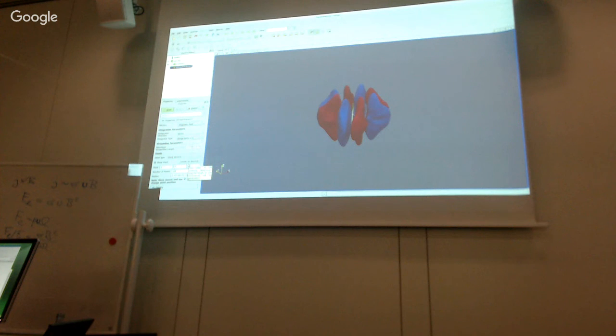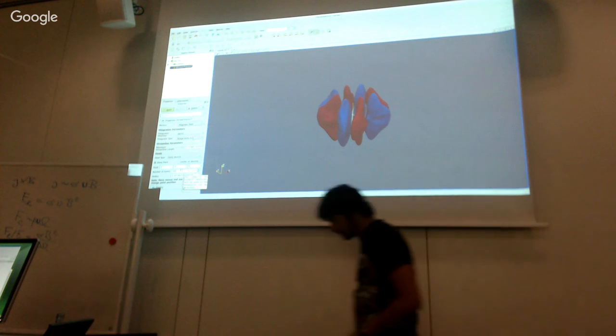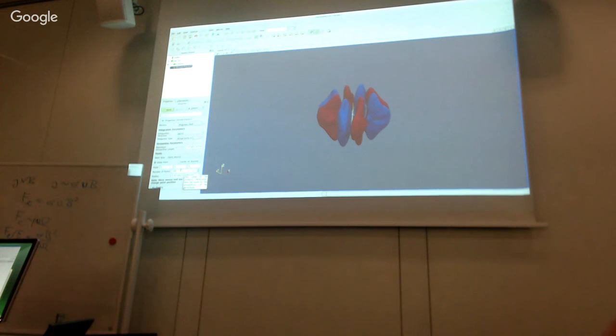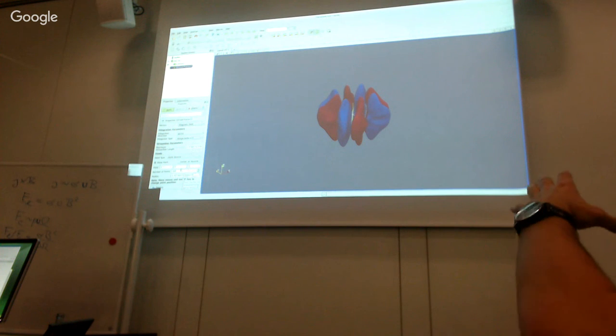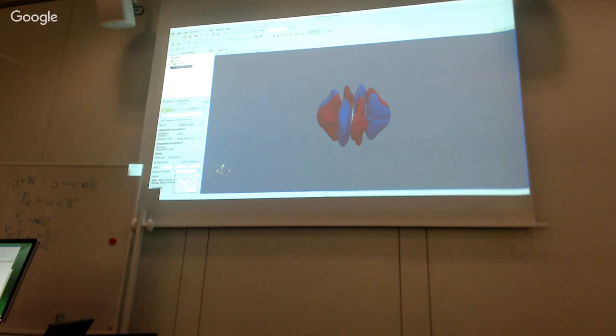You don't touch the advanced options. What ParaView does is that it spreads some random seed points throughout your domain. And for each of these seed points, it tries to calculate the field line which passes through the seed point. By default, it's just putting some random seed points throughout the spherical domain. And this is the radius it picks up by default, so 0.3. So obviously here there is a little issue because the spherical shell ranges from 0.5 to 1.5. So you have to increase this value to the outer radius, so 1.5, let's say.